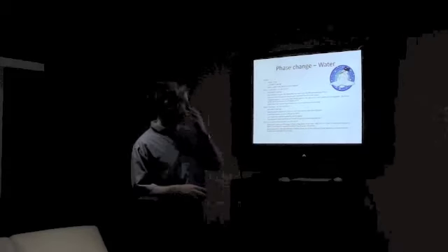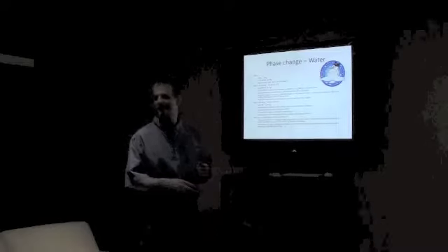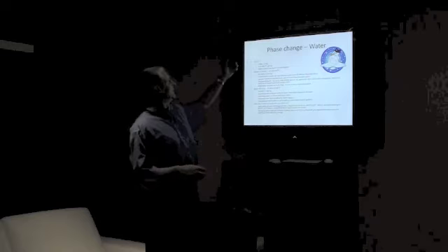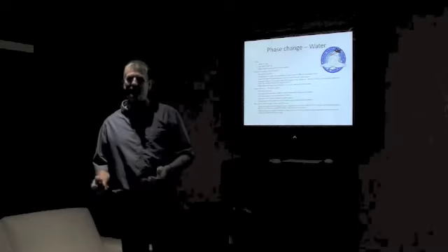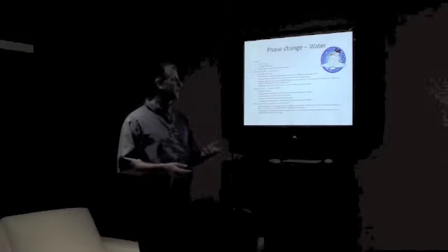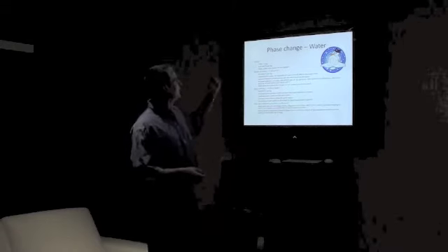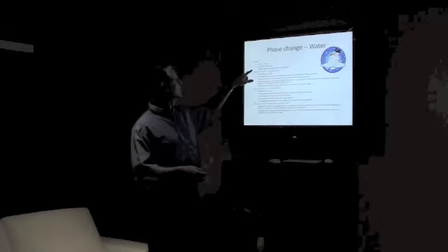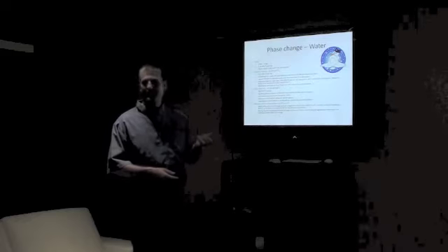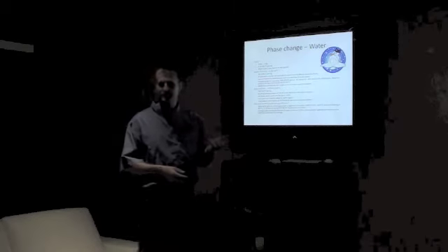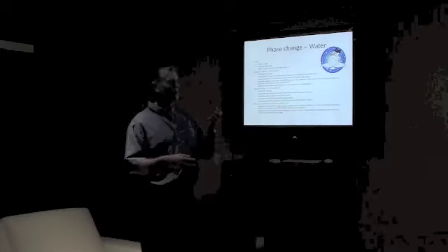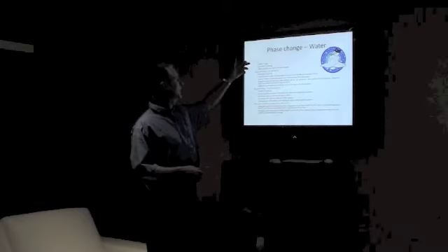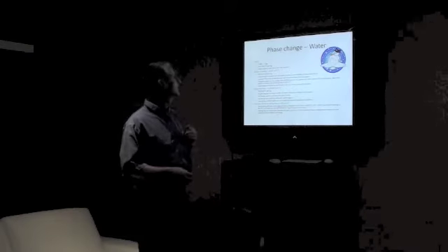Now I want to talk a little bit about water and the different phases and states of water. Some basic numbers and data. So a liter of water and a kilogram of water are about the same. A liter of water weighs about a kilogram. And to heat that kilogram of water or liter of water requires about 1.1 watt hours of energy to heat at 1 degree Celsius. Or conversely, if you want to draw heat out of it, you can get heat at that rate, depending how many kilograms you have and how many degrees Celsius you cool it.